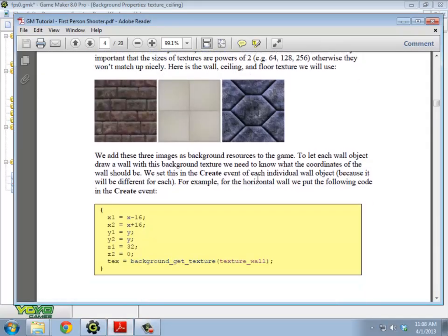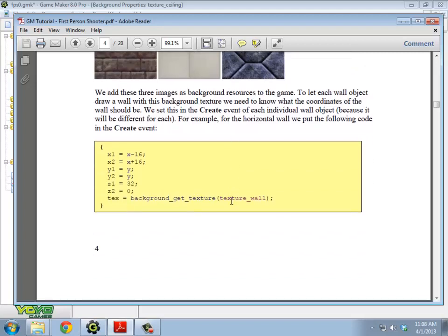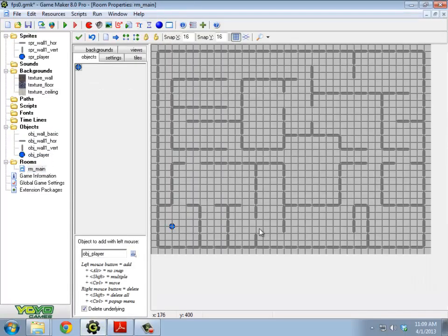So at the moment, none of the walls are going to show up in 3-dimensional space. We actually have to tell it where to draw them. So we have to give it x, y, and z coordinates. x and y are the same way you think of. If we look at this room, x is still left to right from this perspective, y is up and down, and z is out of what we're looking at, so out of the floor. Positive z is closer towards our eye, and negative z would be into the floor. So when we're talking about z coordinates, we're talking basically the height of things in this room.